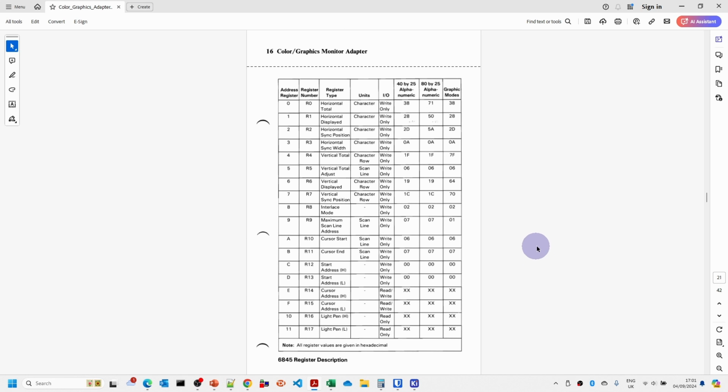Now these timing values, which are the CRTC register values, will all be different for the Breadboard PC because we're going to be doing VGA output, which has different timings from this. We've already made those changes for MDA in the BIOS, but we're going to have to make similar changes in the XI8088 BIOS for our hybrid CGA VGA timing card.